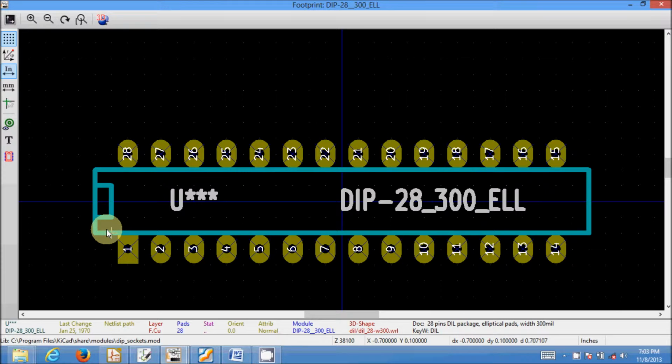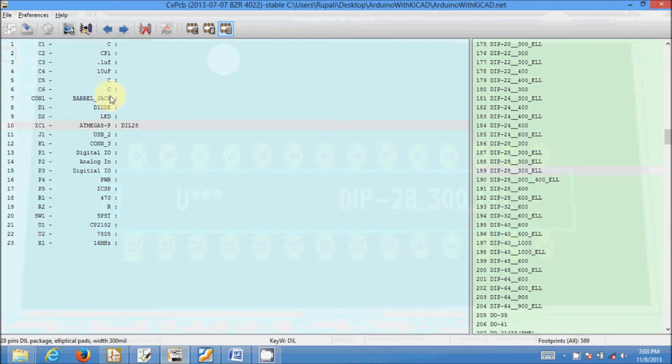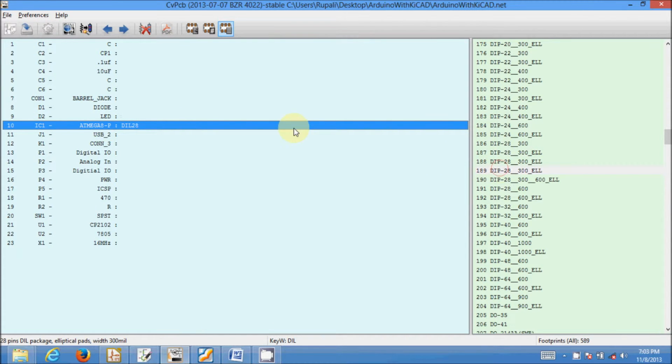It's very important that you verify all the footprints that you put in the design. With standard components, it is pretty common to use the library footprints, but always make sure that you measure the footprints before you put them in the design, because there's little that one can do after you get the boards fabricated.